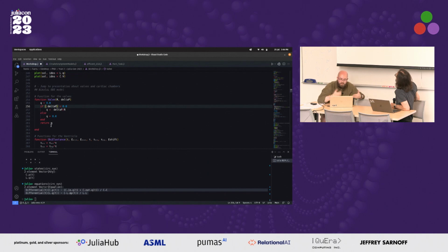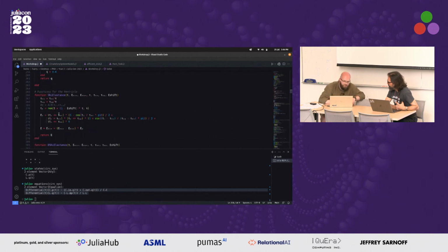But otherwise, that valve's going to be shut, and that then means just no flow's getting through. We assume infinite resistance. So you're assuming that on-off. Yeah, no area change. Not in this simple one; we'll look at a more advanced one and how we write that later. So just on-off, which is the standard in most lumped parameter systems. If it's open, flow through divided by the resistance. Otherwise, no flow at all.